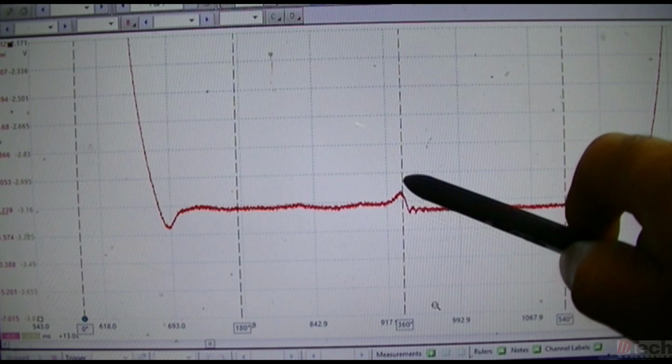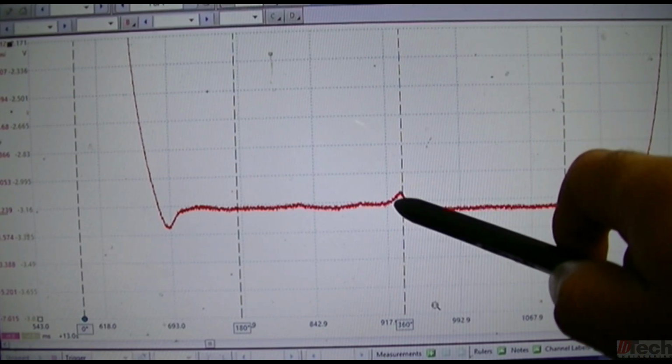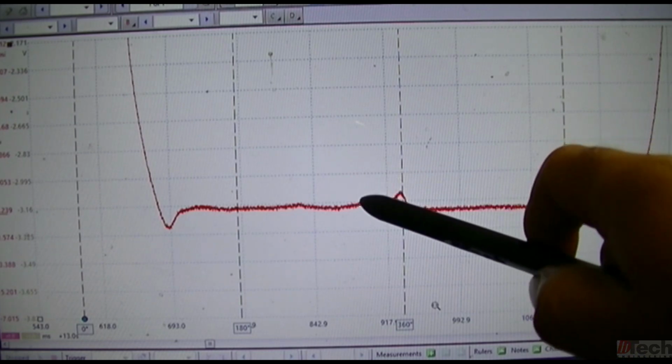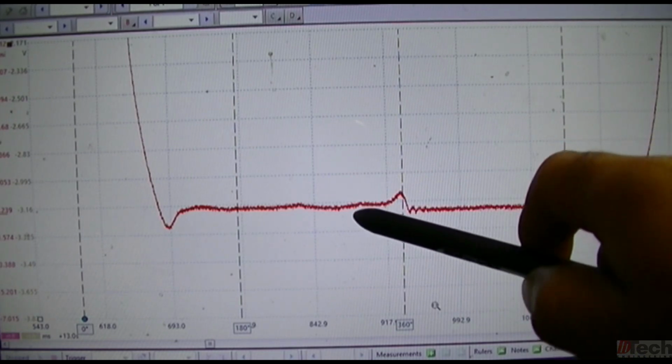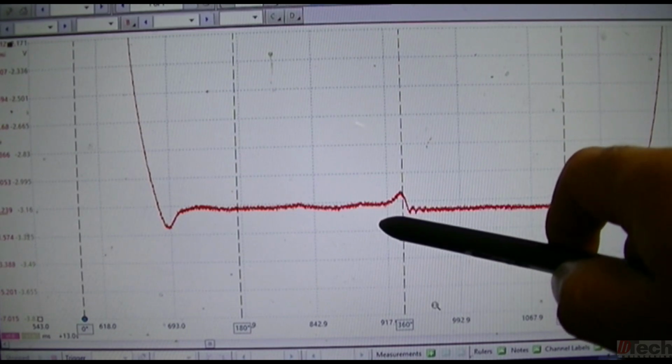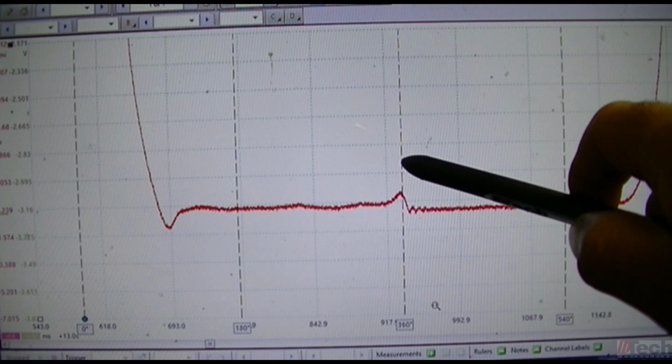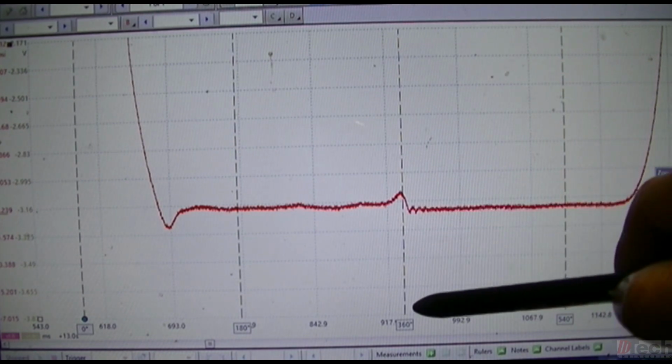So the piston going up will raise the pressure, but if it's typically higher bank to bank, that means one probably closed earlier, had more time to build and raise the pressure until either an intake valve opened or the piston started to descend.